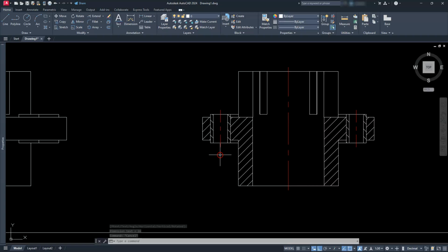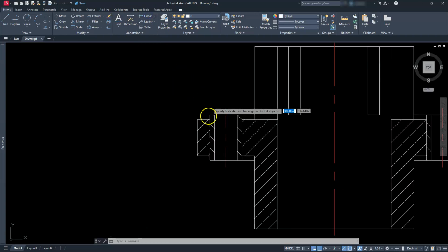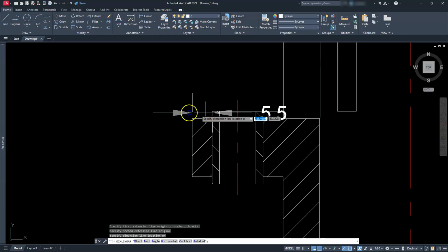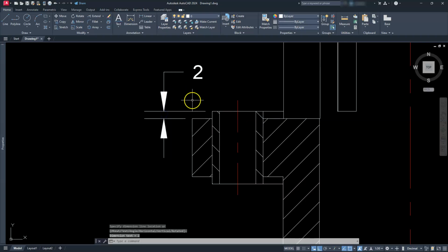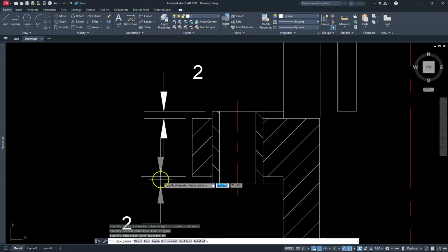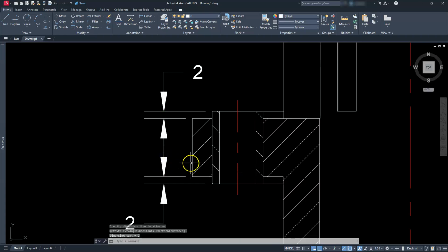Let's go ahead and take a look at our section view. Let's do a linear dimension from this endpoint to this one. And I'm purposely picking it in that order so I can throw it up at the top. Meaning that I'm going to do a linear dimension from here. If I select the inside first and I select this as my outside, it remembers the outside is the side that you want to put your dimension on.